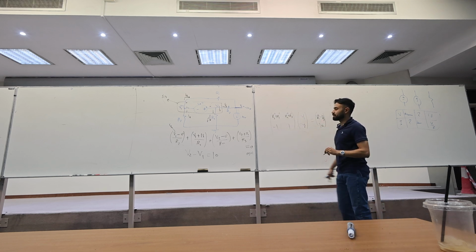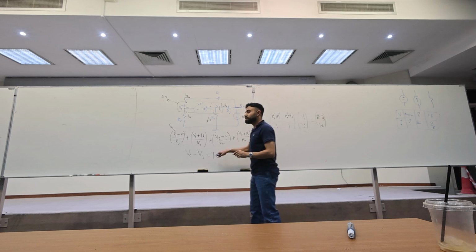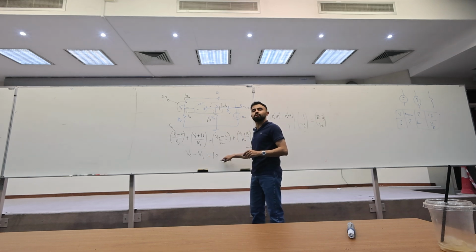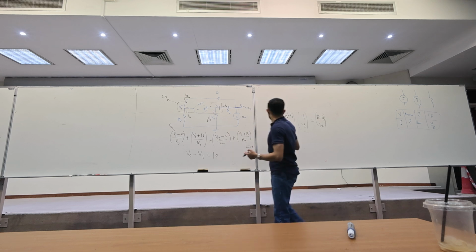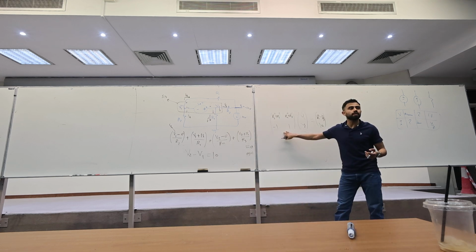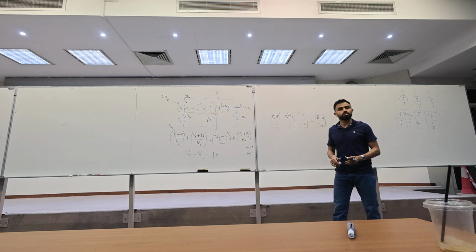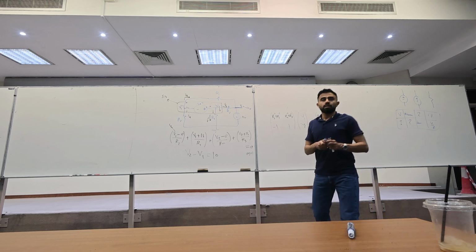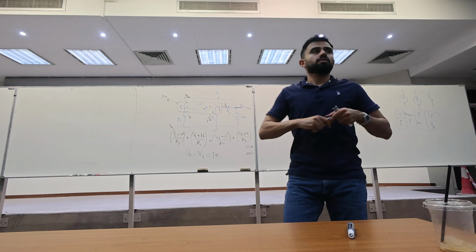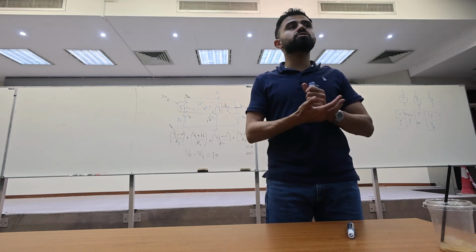Keep in mind the constraint equation is always equal to something, so no need to shift it. Okay? And then you solve the system, and now you have solved the supernode. I think the two remaining problems are easy now.